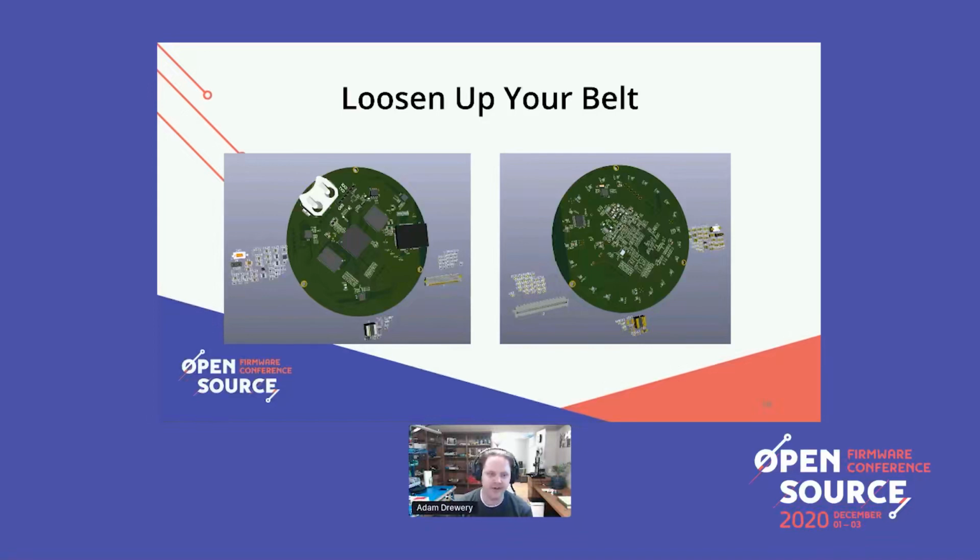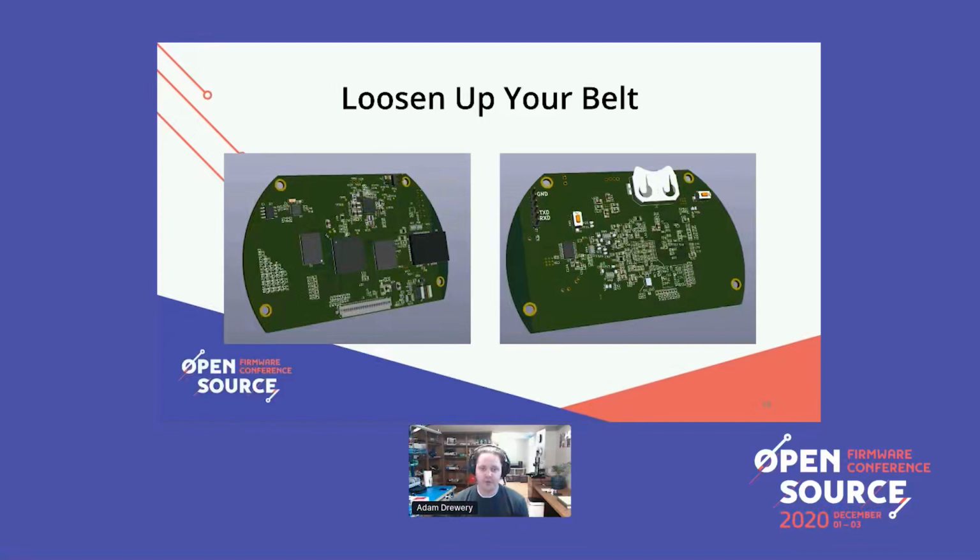What I'm really getting at though is you want to give yourself flexibility to change. In this particular project, we were at this point and we realized, man, we're going to have to put a display right here. That's going to cause problems with all those parts right there. So we decided to change. We moved the circuitry to a different board. We left that other stuff, the LEDs and all those other things on that other board. And we just interfaced those two boards that actually wound up leading us to the solution that we really wanted.